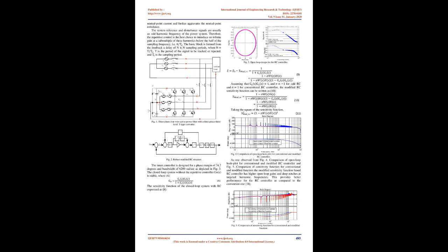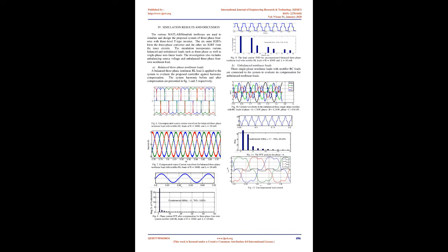On the other hand, zero voltage on the AC side is achieved with switching on TX3. Following this switching effect, the compensation current increases for positive phase voltage and decreases for negative phase voltage, VSx. As a result of this switching effect on any phase, a unipolar voltage is obtained on the respective phase of the AC side of the T-type converter. The state space model of the T-type converter is defined as 16.